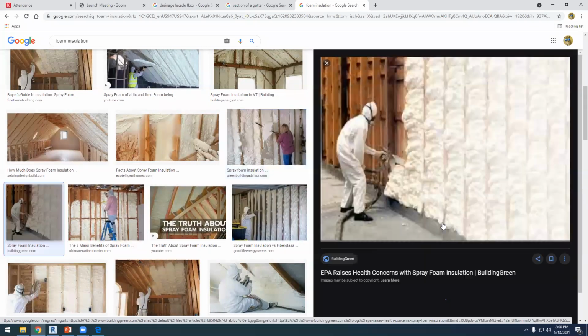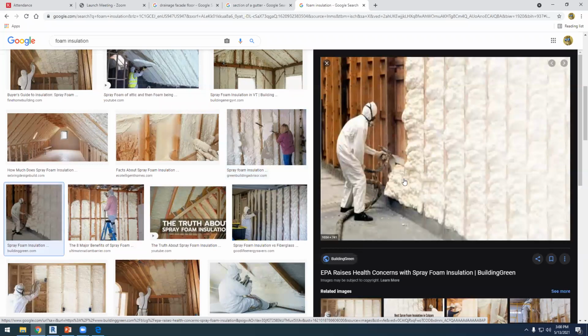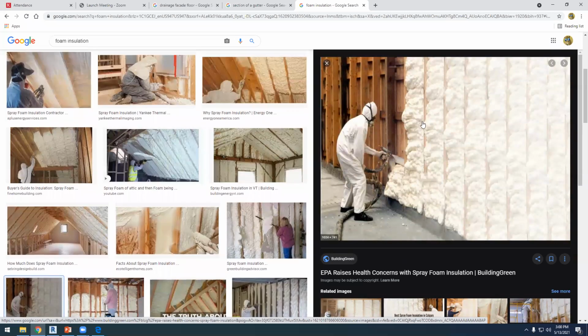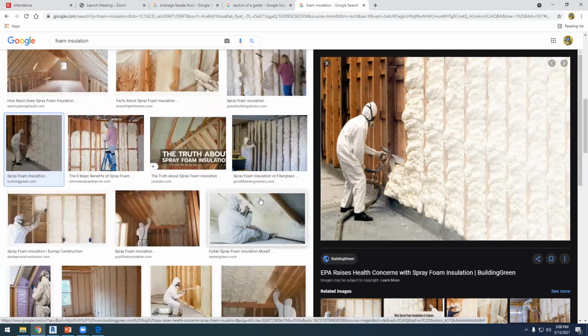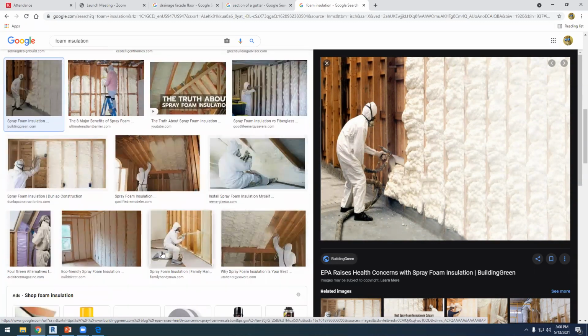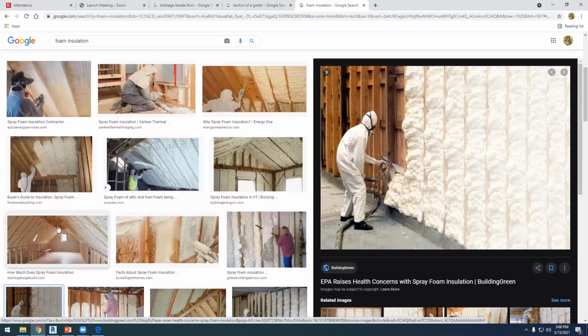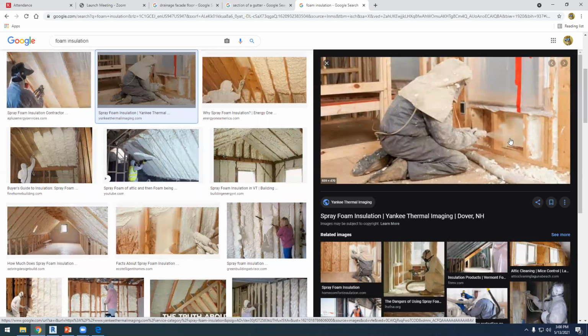But this is the kind of thermal insulation that we have to fill small gaps. You can even use this foam instead of a rigid panel. We can project this foam on the wall, and then it dries out, and then it becomes something solid. Originally it's something like foam. But especially this is very useful to fill small gaps like this.